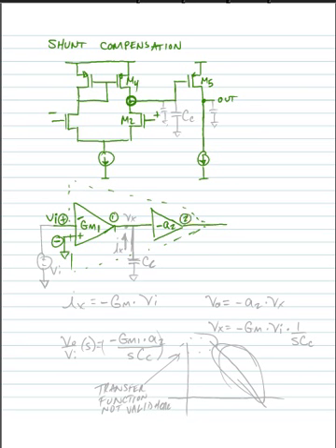Normally we would have some parasitic capacitance at this node and some parasitic capacitance at this node. And what we're going to try and do is add a capacitor at this internal node that's very large. So we'll call this CC. So what we're doing is adding a capacitor at this node called CC. Now if you were given an uncompensated op amp, sometimes they might put a pin at this node so that you can add that compensation capacitance externally.